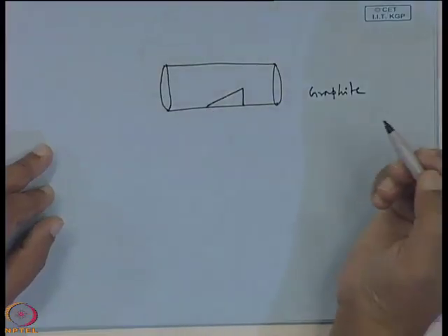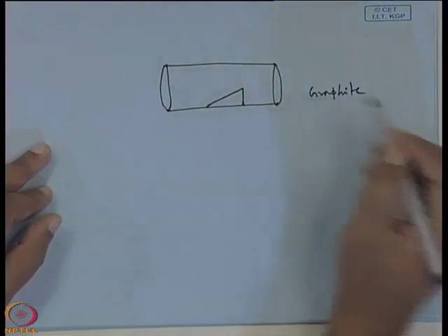Okay. So, now one question arises: if your gas or the vapors contain oxygen, then can you use a graphite block as susceptor? No, you cannot, because at that temperature oxygen will react with the graphite, right. So, if you use a gas or a vapor which contains oxygen, then what are the susceptor materials you can use?